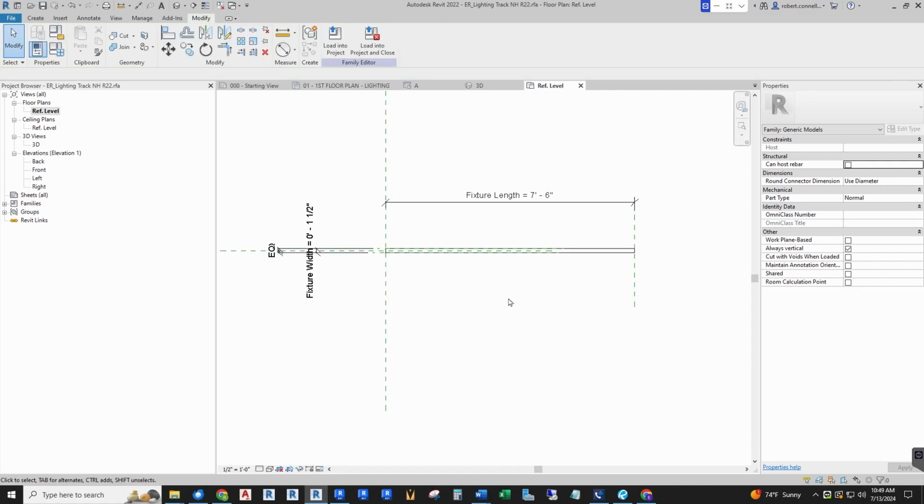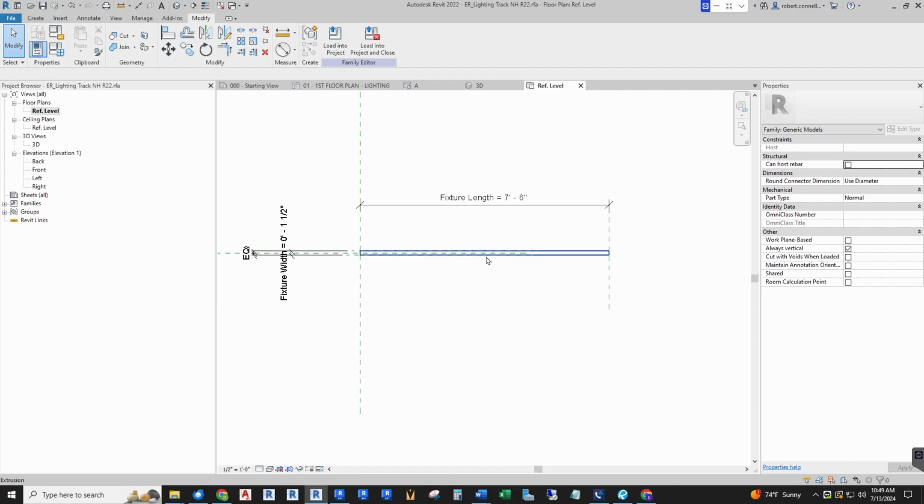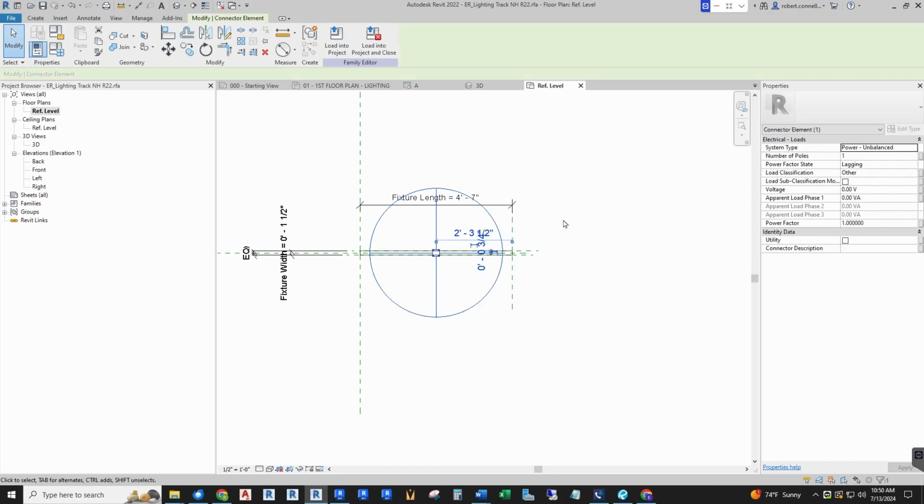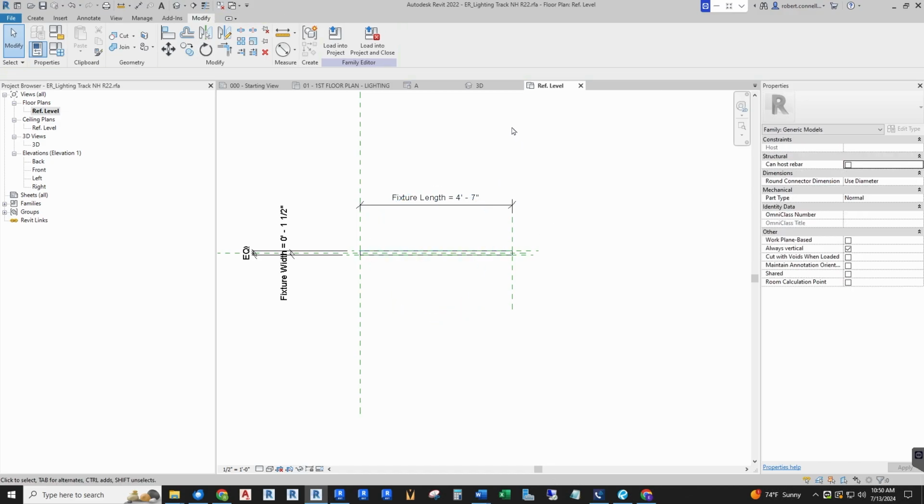In the model itself, there will be a little connector point. And if you're trying to do that manually, find a manual connector point, it's hard to do it if it's floating out in the middle. So, for example, if I said create electrical connector, and I just chose that, see how it's in the middle? Now, whenever I move this dimension, it's going to be floating, and I'll have to find it in my model. I'd rather have this kind of pinned over to maybe one end of this. So let's get rid of that. And I'm going to try and pin it over here.